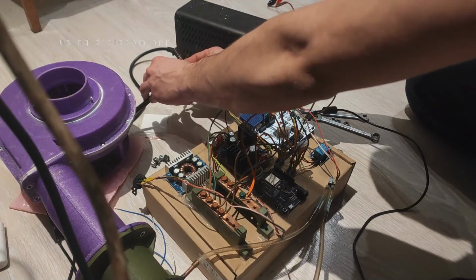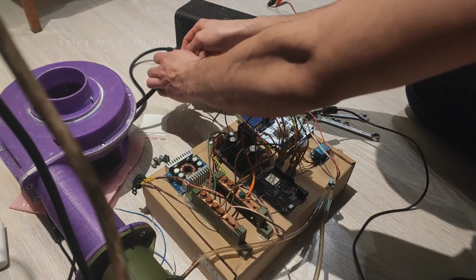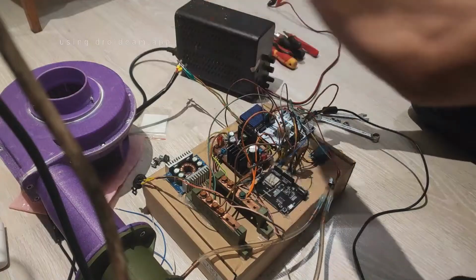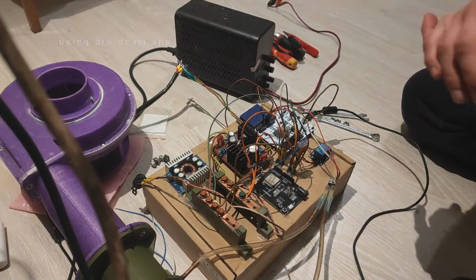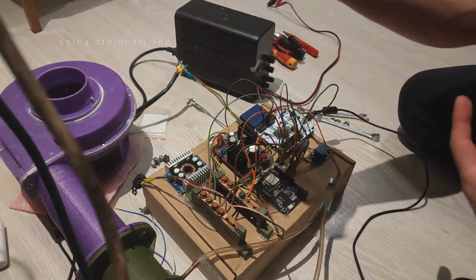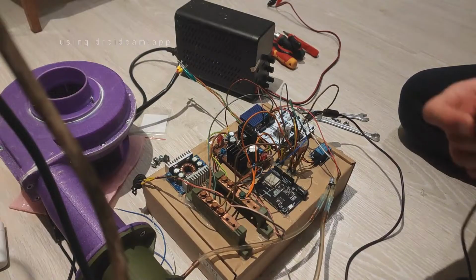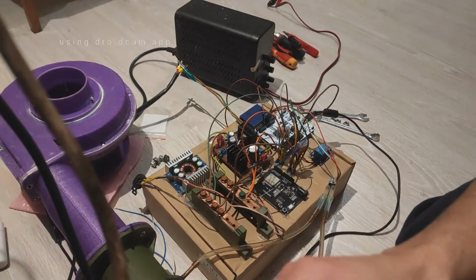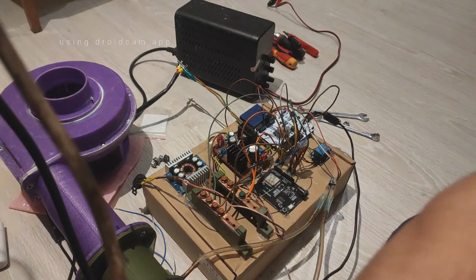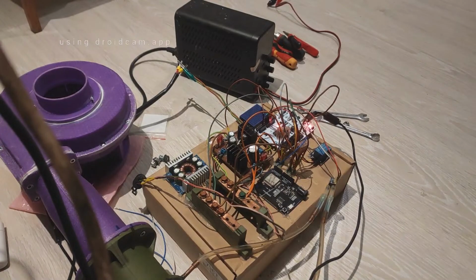So this is the green, so the power goes to here, because I always say this, but I have actually found out the design of the rotor of the blower is designed the other way around, so it is a counterclockwise design, not a clockwise design, because the other motors were like that, but this isn't. Very interesting. I need to hook the motor the other way around.